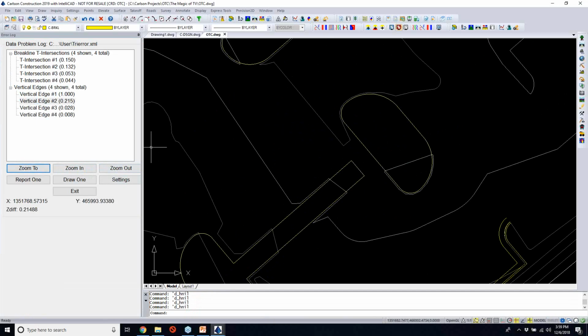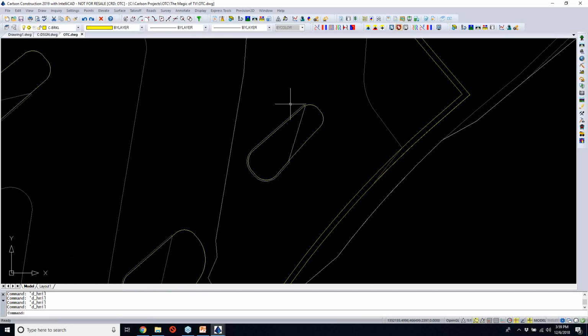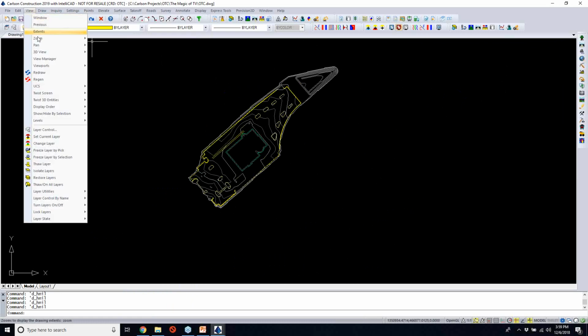Okay, so the software is telling you where you have some problems. So ultimately, for a more accurate surface model, you're going to want to fix these problems. For right now, where these contours cross my curb islands, I'm not going to worry about that right now. They're very small, sort of minute, so I'm not going to worry about it. But I've now got basically my surface models built. We'll take a quick view at them, and in my 3D viewer, we'll take a look.